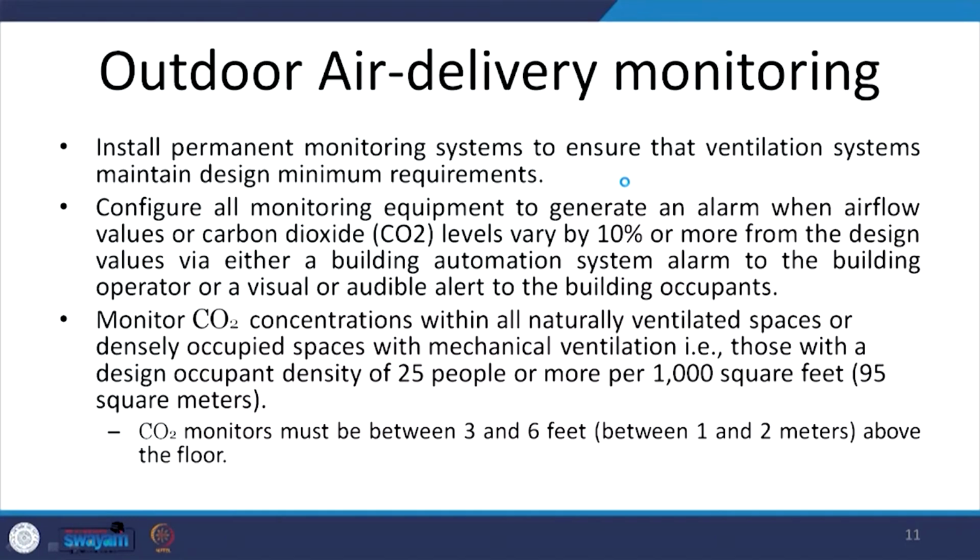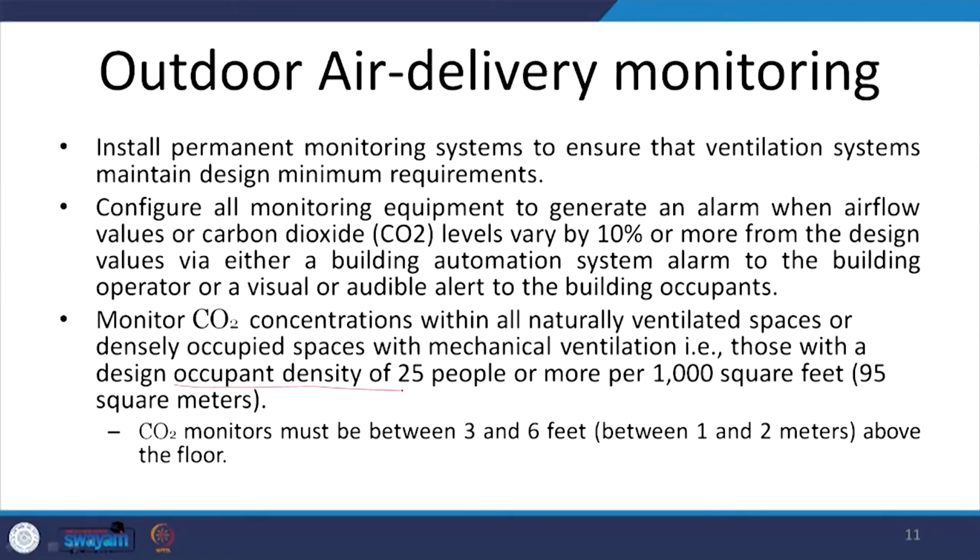The next is outdoor air delivery monitoring. So, it is not just the rate of supply of air, but it is also the monitoring of the quality of the air which is being supplied indoors. Wherever the occupant density of 25 people or more per 1000 square feet is present, monitoring of CO2 concentration is mandatory. CO2 concentration has to be measured and maintained within the threshold limit of 1000 ppm.